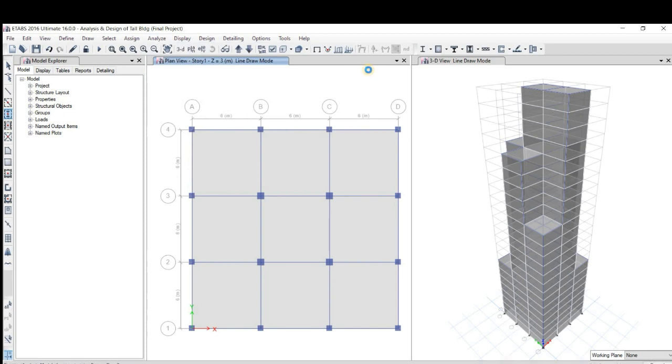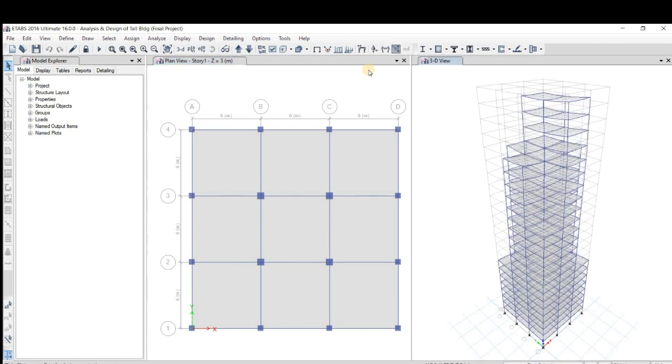It will take some time. After that, the run analysis is completed. The frame structure will be like this. These are the deflection values, slope values and moment values on the screen. If you select any beam or column, it will show the ux, uy, rotation ry, and shear moments. If you move the cursor to any frame, the joint, element and story values will be shown.